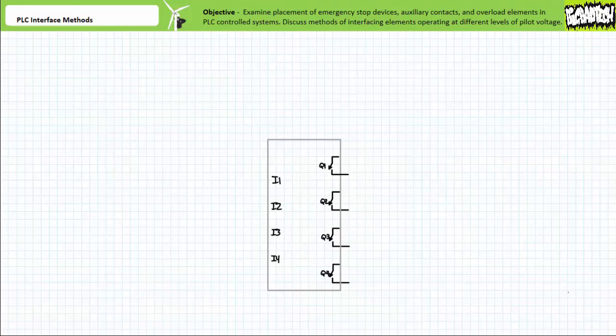Although this separation between pilot and primary signals should be simple in concept, complications to this methodology exist when we introduce a radically different means of control in the form of a programmable logic controller, or PLC. PLCs are industrial computers that, in summary, examine inputs, run a program, and issue outputs. PLCs, barring some peculiarities, closely mimic the behavior of those systems employing hardwired relay-based ladder logic. However, they are flexible, reprogrammable devices that make quick modification of a system possible without the time-consuming necessity of physically rewiring it. Two important complications exist when PLCs are introduced into the mix.